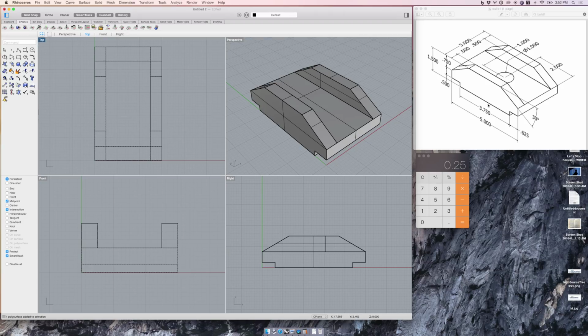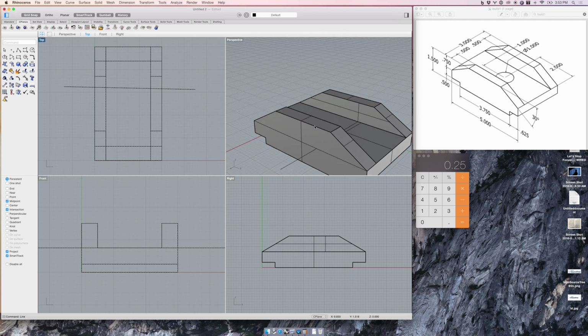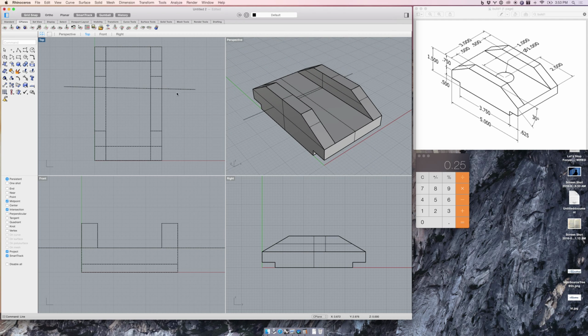But real quick before I do that, right now it's along the bottom. How far up do I need to shift it? I'm going to argue that I need to shift it up 0.75, because I need to go this 0.25 and then an additional 0.5 to bring me right on level with this. So let's try that and see if it works. I'm going to shift the elevation up and move it a distance of 0.75. And then again, that easy test is just draw a line and check to see if it's actually flat on that surface. And it is. So I've elevated my C-plane.